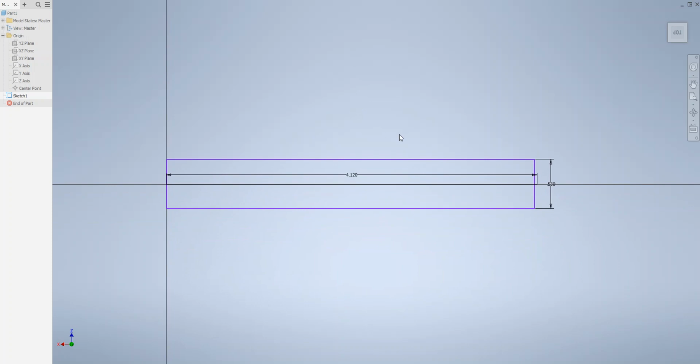So again, because we know this is going to be an outline, just an outline, we can do some modifications here, obviously. And to do the modifications, I need some fillets at the end. And usually the right side of the rectangle is going to be forming a handle, and a handle is supposed to be not sharp corners. So we're going to have to use the fillet command.